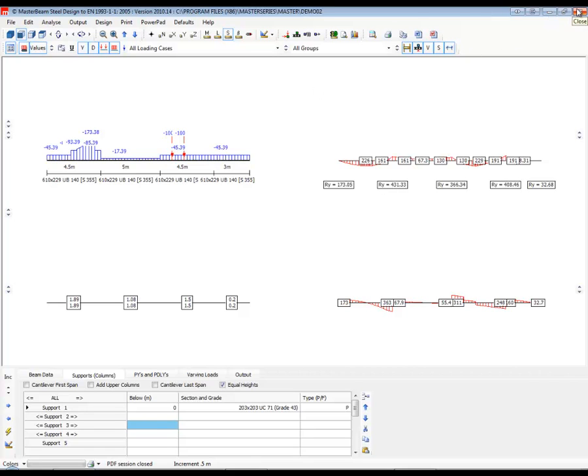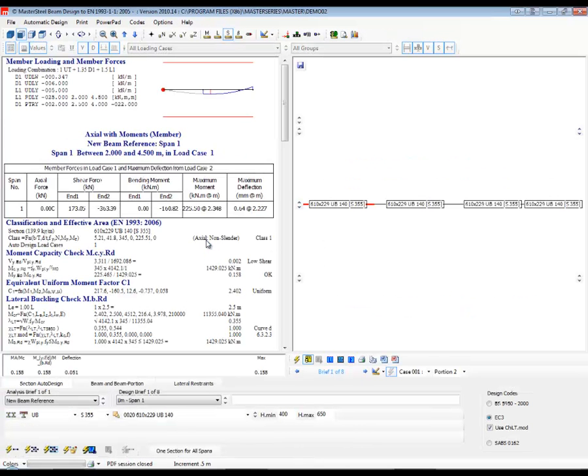So that is the same. It's the same program, just the commercial version you have up to 16 spans. If you have a power pad license, you get a 3-span version of this. So we'll go back into steel design, and it's slightly more significant because we have 8 design checks.